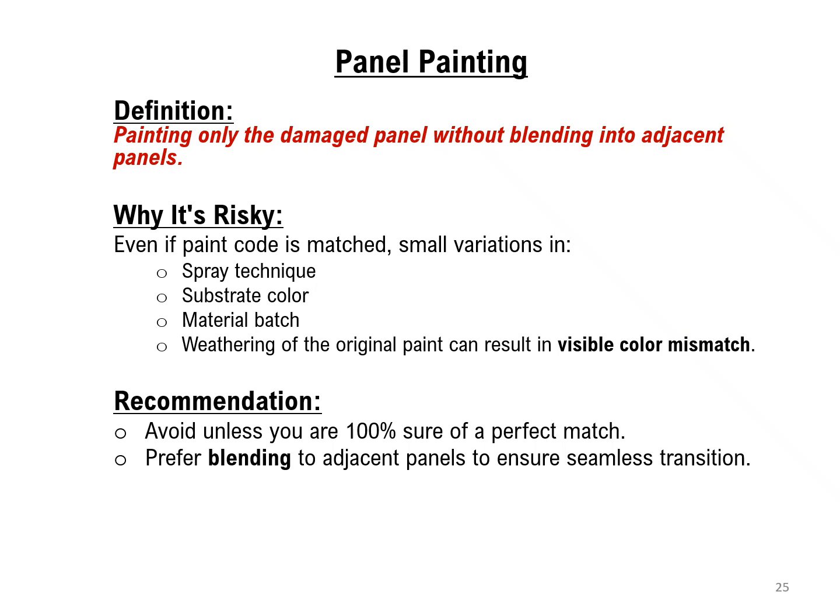And lastly, what is meant by panel painting? Panel painting is painting only the damaged panel, without blending into adjacent panels. Why is it risky? Even if paint is matched, small variation in spray technique, substrate color, material batch, or weathering of the original paint can result in visible color mismatch.